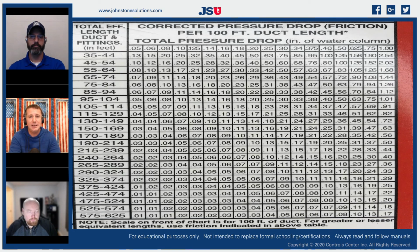So if we're calculating from 100 feet of duct length, we're typically not going to have to do much recalculating. But as we start increasing our duct sizing beyond 100 feet, we have to do some correction factors so that we get the proper size duct for the CFM that we need. So it's a good chart to go over. It's a good thing to understand.